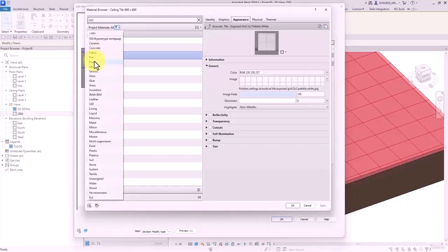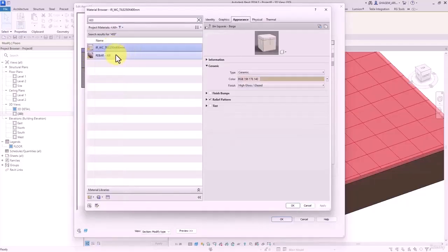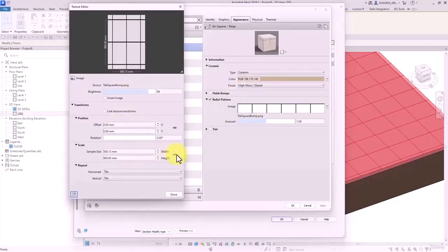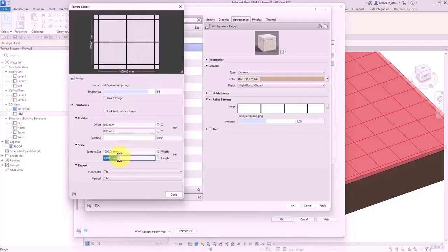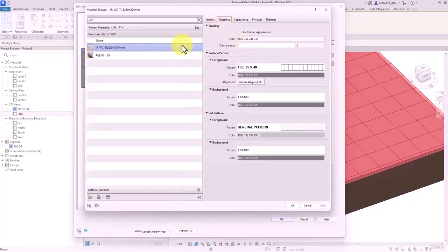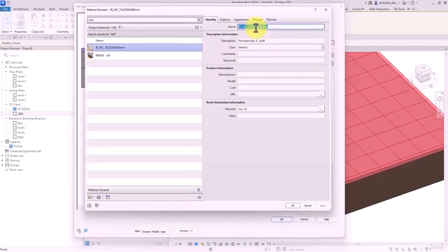Let's see what we have. I change this one to floor. This one, for example. Okay, I change this. I just select this, and I want them to be 50 by 50. There are two tiles, so they will be 1000 and 1000. And be careful when you are entering values according to scale, the number of tiles should be multiplied in one of them to be able to have the correct value. Except for this, every value will be incorrect.